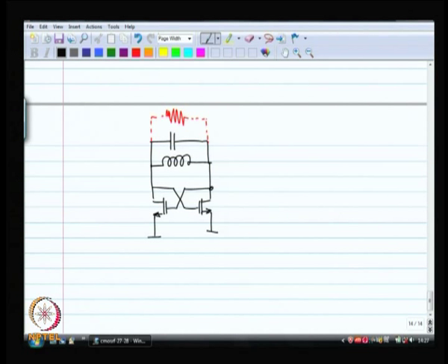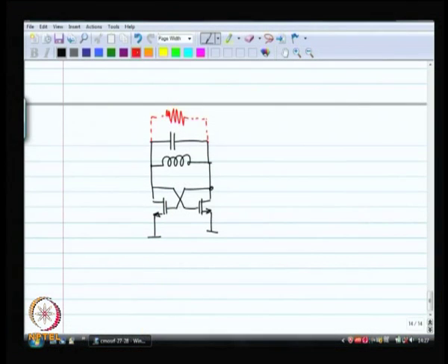This works when you think about the small signal. What about the biasing of this? These devices need to be biased, right. Should not forget the biasing of these devices, and if they need to have any kind of GM, they need to have some DC current going through them. There has got to be a power supply. So, supposing I need some current like this as far as DC is concerned, how am I going to create a current like that?